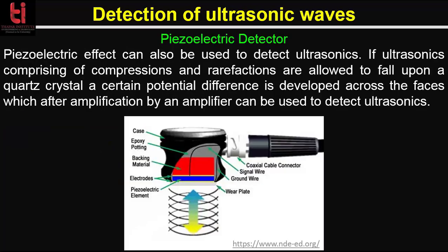Now, coming to the detection of ultrasonic waves, there are actually a variety of methods to detect them. An ultrasonic level or sensing system requires no contact with the target. For many processes in the medical, pharmaceutical, military and general industries, this is actually an advantage over inline sensors that may contaminate the liquids inside a vessel or tube or that may be clogged by the product.